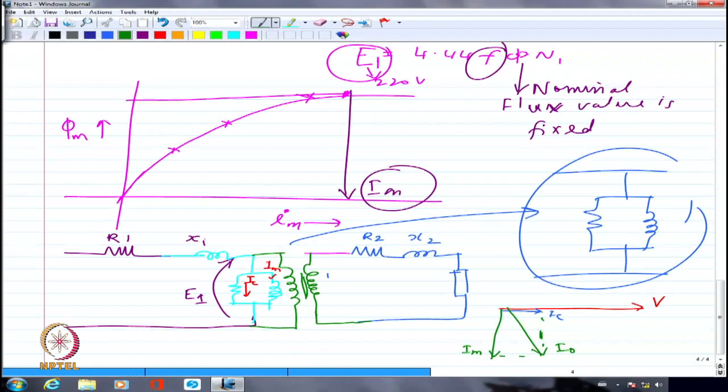That is what is my no load current. So the no load current of a transformer consists of two portions. One corresponds to the core loss component of current, which is fictitious. And the other one is the magnetizing current drawn by the transformer, which I would not say is completely fictitious, because you need that MMF definitely to establish the flux. But only because you establish the flux, the core loss is also happening.